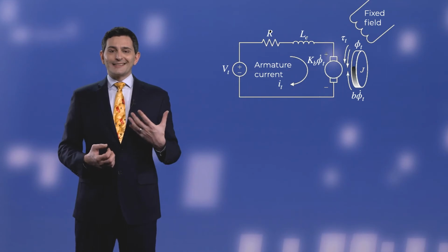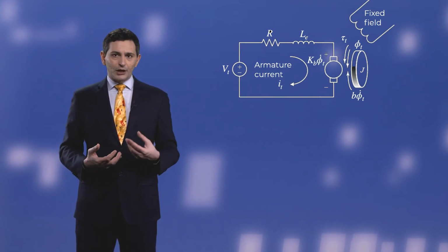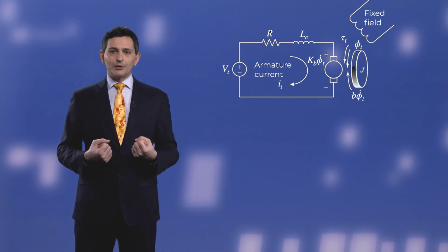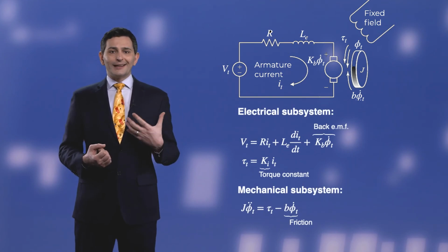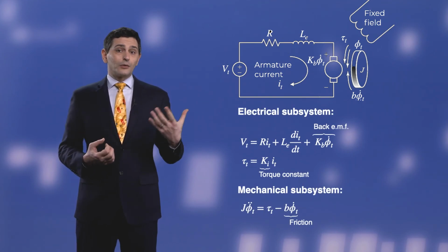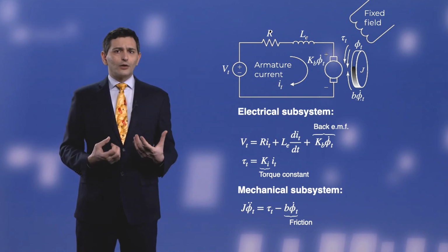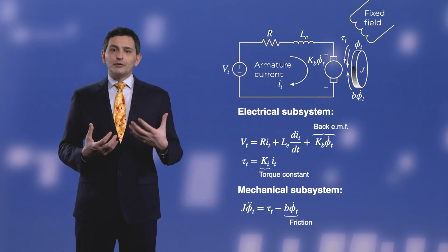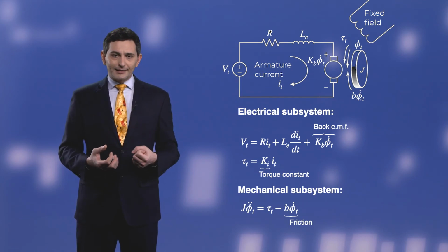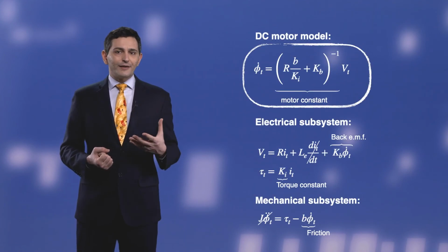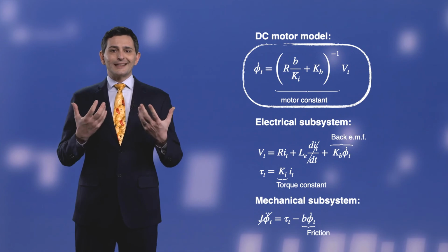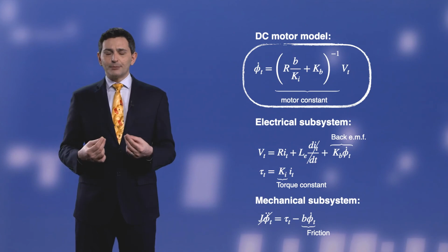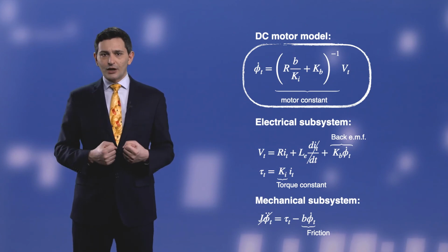The motor can be modeled as an RL circuit having two sources of voltage, the input provided by the user and the back EMF induced by the rotation of the shaft, which resists the motion. Motor equations include an electrical and a mechanical subsystem. The electrical one is obtained through the Kirchhoff laws, the mechanical one by imposing equilibrium of torques on the rotating shaft. These models include several constants, which are typically determined experimentally. The dynamics of the motor is much faster than that of the robot, so we can assume steady-state behavior. By neglecting the derivative terms, we obtain an instantaneous relationship between the applied voltages and the wheel angular velocities.